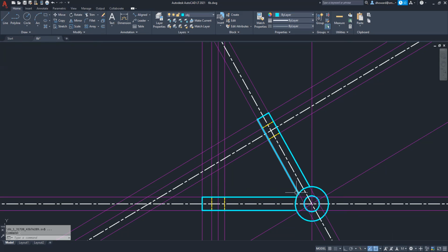We're going to start with the 1 1/4 dimension that we are given from center here over. It is 1 1/4 inches. So enter 1.25. There it is. And now that I'm done with that, I'm going to show that as the center line. Okay, so again, from the center over, it was 1 1/4 inches.